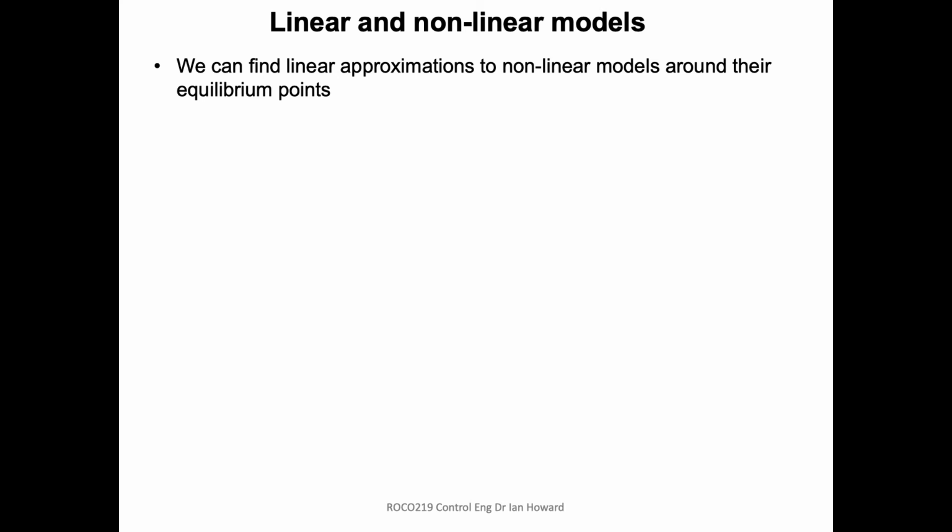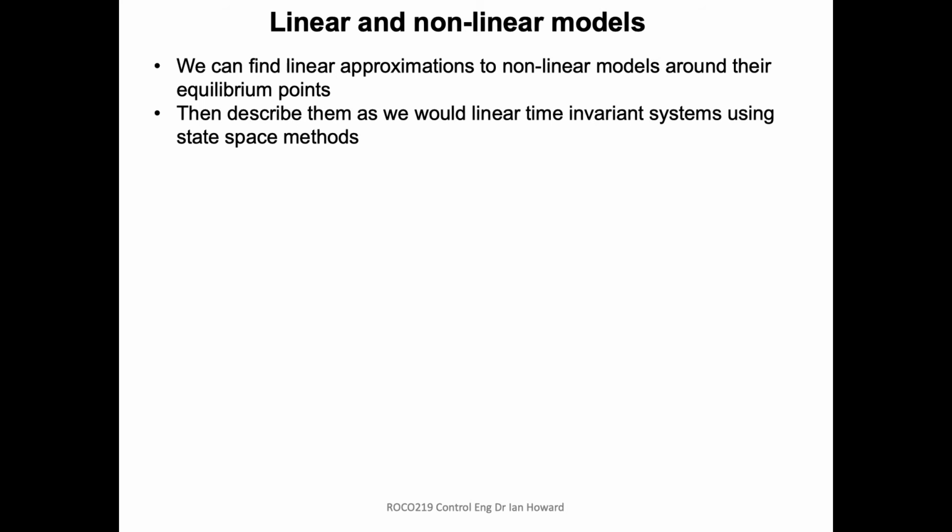So think back to our inverted pendulum. What we're doing is balancing this pendulum. Normally in the inverted condition it's in an unstable equilibrium. It's standing up and it would fall down if it wasn't for the controller. There's another equilibrium, of course, when it's dangling downwards. These are the two conditions we have to consider as equilibrium points for a pendulum, and that's generally where we want the system to be. So it makes perfect sense to linearize around those points because those are the ones we want to use. You can also linearize about any point in general, because that's the idea of linearization.